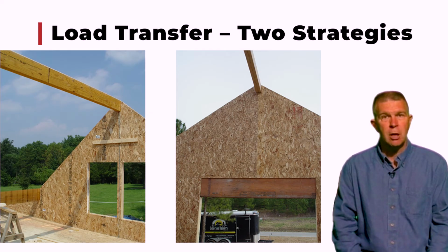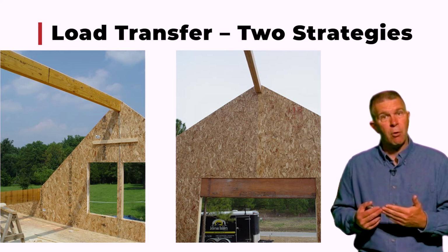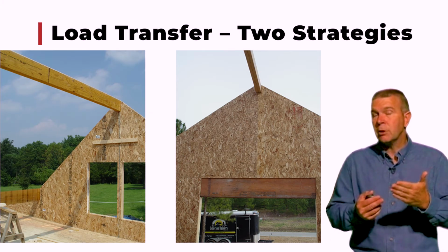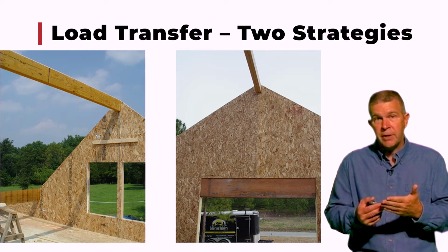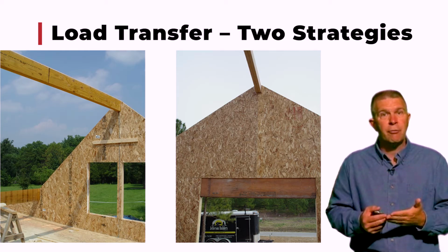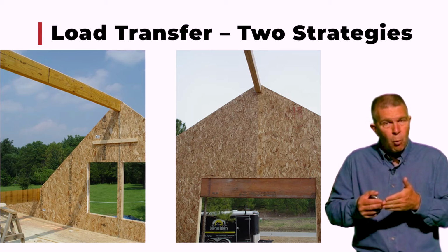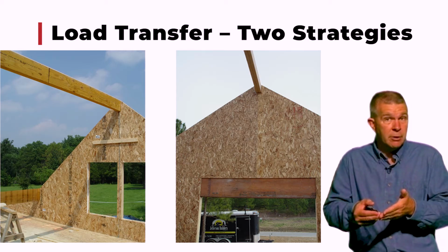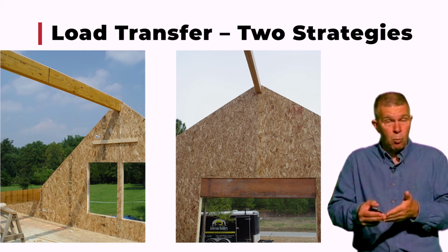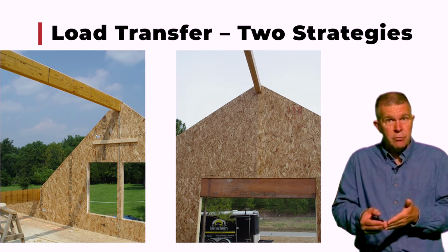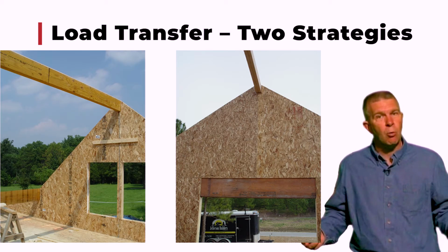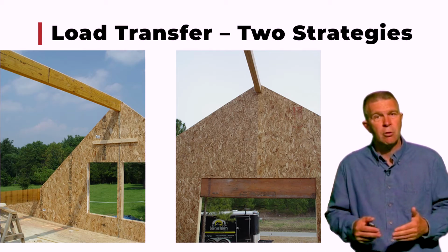the foundation below. If we look at the picture on the right, we're dealing with a very similar situation in that we have a ridge beam and we're posting down through, but we're hitting that header. And once we hit that conventional header, that point load has been determined that one, a header is needed, and the posting, when transferring the load to the header, now carries that load around the window opening into jack posts and on down.